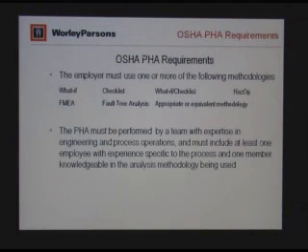And the OSHA requirements for the process hazard analysis is the employer must use one of the following methodologies: one is what-if, checklist, and the what-if and checklist combination, and the HAZOP, and the FMEA, which is failure mode effect analysis, and fault tree analysis, or other kind of equivalent methodology.